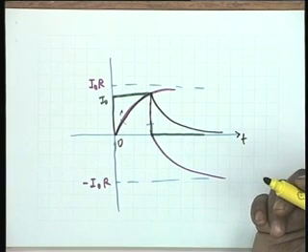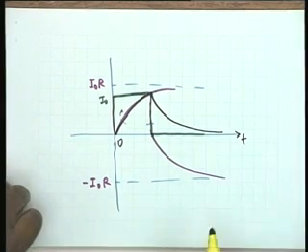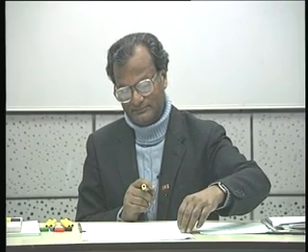You must not divorce physical concept, because circuit theory is a mathematical subject. In fact, in no mathematical subject related to engineering should you lose sight of what is happening physically. That is your best weapon. The best weapon of an engineer is physical insight. So after the source has been removed, the pulse is over, the source places a short circuit. Open circuit, because that was the switch, and a current generator removed means it is replaced by an infinite resistance. A voltage generator removed means it is replaced by a short circuit.